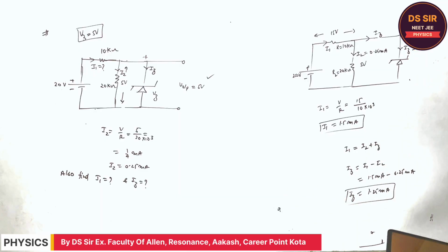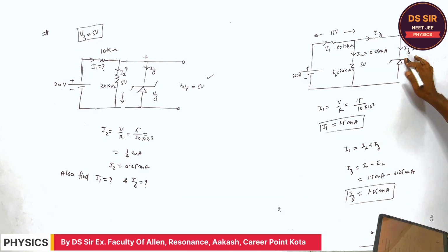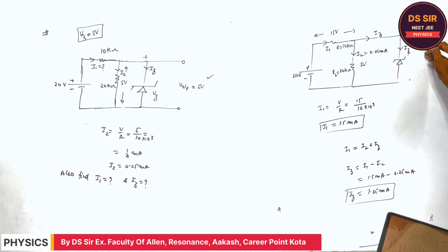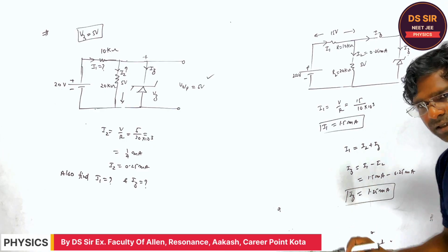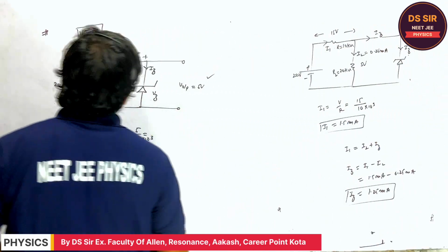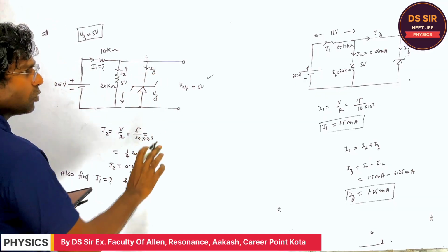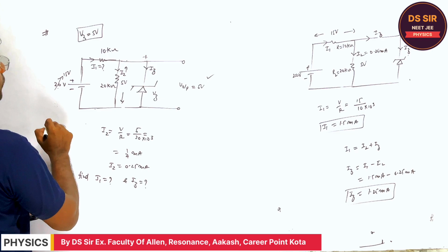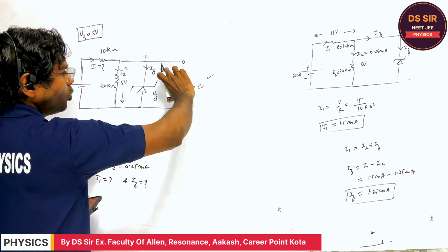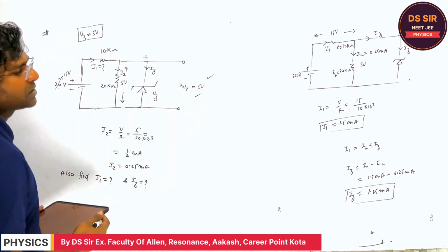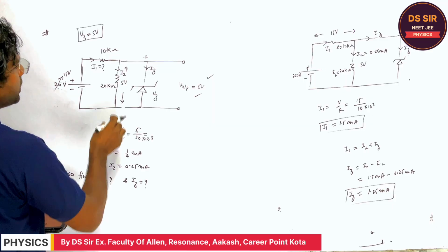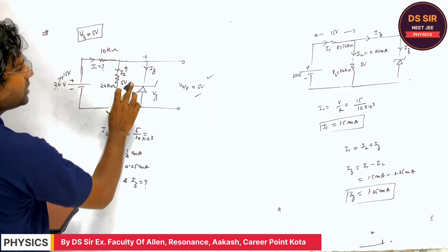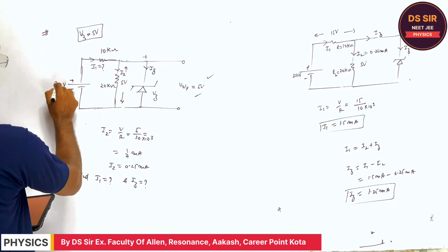You tell. So what is the Zener diode current? Zener diode current is 1.25 milliampere. Is it clear, Sanjay, or not? It is not the same. So listen one more thing. If you apply 15 volt in place of 20 volt, the output voltage will remain always 5 volt. Only the current I1 and IZ may change. Do you understand or not?